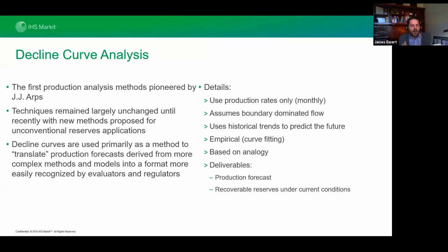So of course, decline curve analysis has been around for a long time. It only needs production rates. It does not need pressures. It also assumes that you are in boundary dominated flow. And essentially what we're trying to do is say, if we have some historical data, we can draw a line through that and estimate what's going to happen in the future to get an overall EUR.